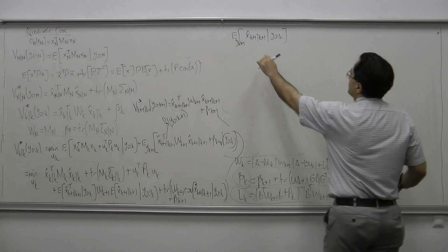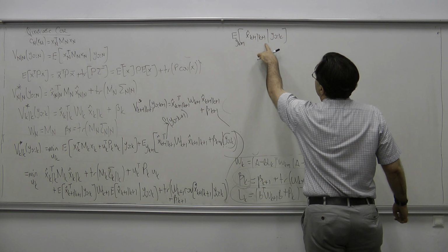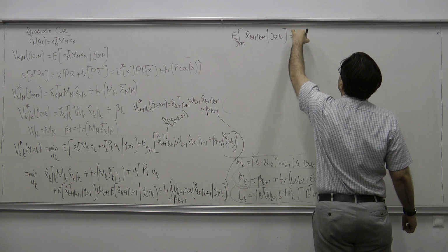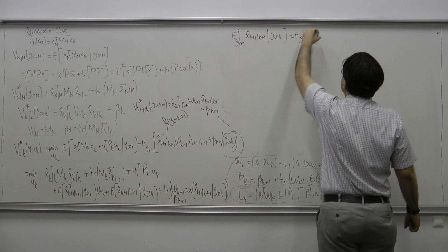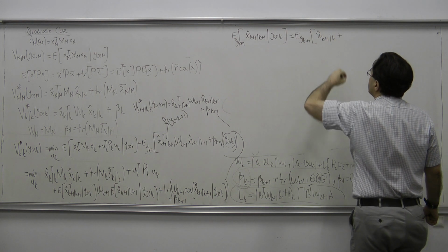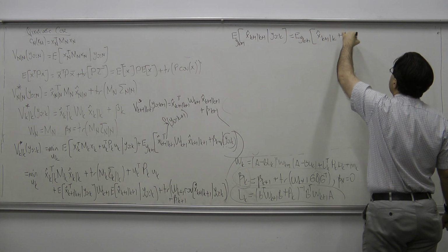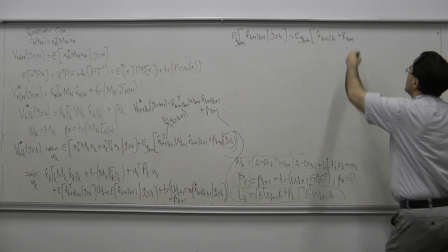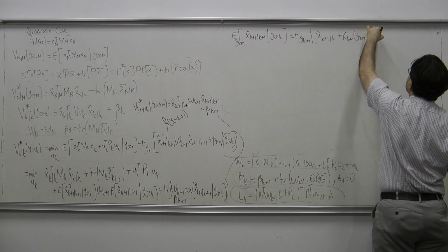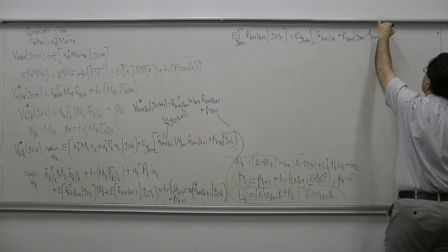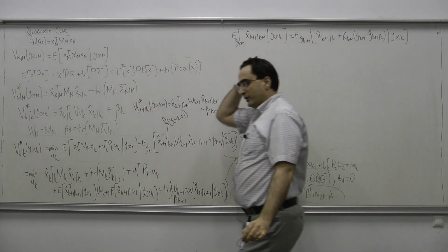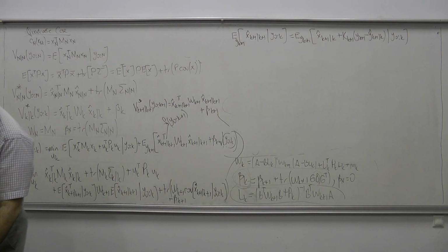So now what I'm going to do is write the formula for this Kalman filter estimate. Expected value with respect to yk plus 1, this is going to be x at k plus 1 given k plus Kalman filter gain at time k plus 1 times yk plus 1 minus y hat k plus 1 given k. Okay, given y0 to k. Okay, it is just this expectation.